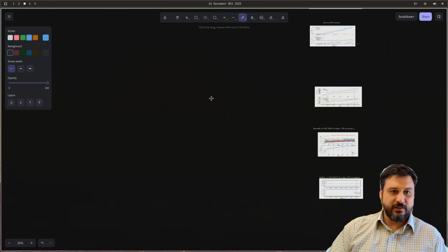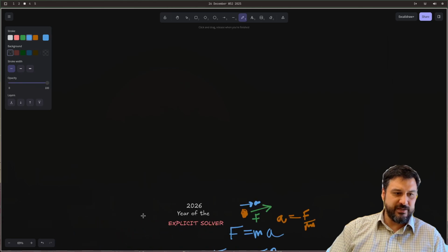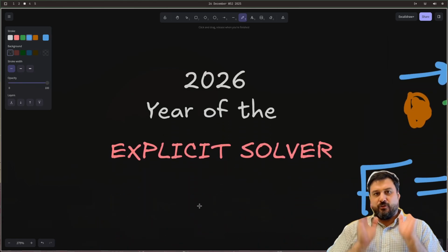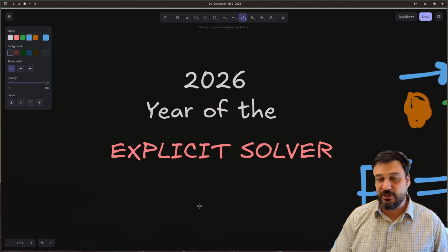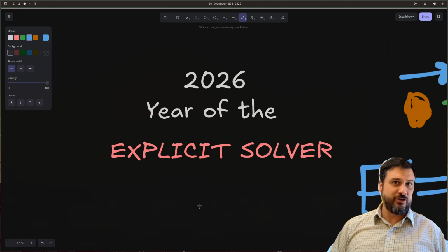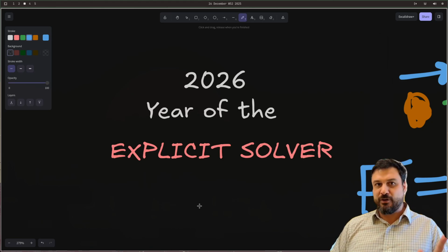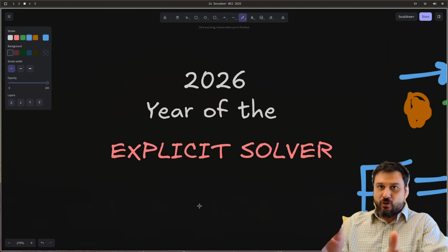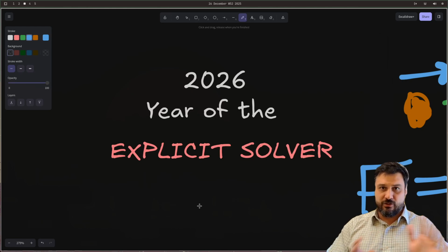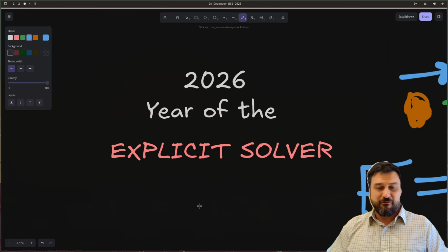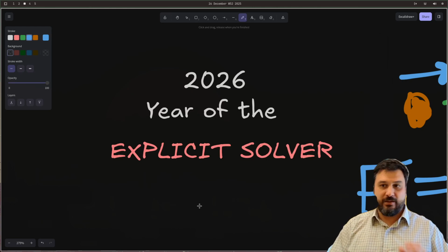So explicit methods are what's going to drive basically HPC for the years to come. I think the really large models are going to be explicit. We need to learn a whole bunch of things before we dive into this. We need to learn how to do statics, and this is a solved problem. This is not cutting edge research, but it just goes to show you, if you want to go high fidelity, you need explicit solvers. Abaqus solved this, LS-DYNA solved this. These are all explicit, or if you're into soils, FLAC also uses explicit, and this is the reason. It doesn't use memory, it's super fast, it's super scalable, and we're set to go.